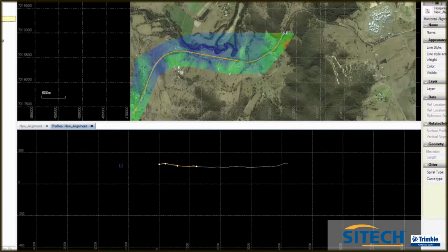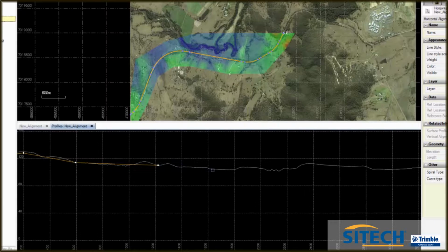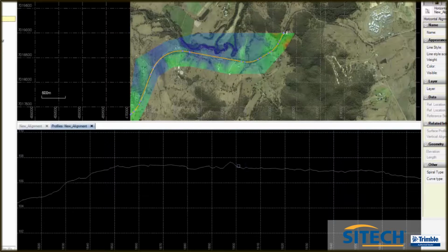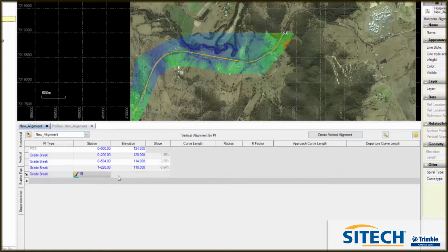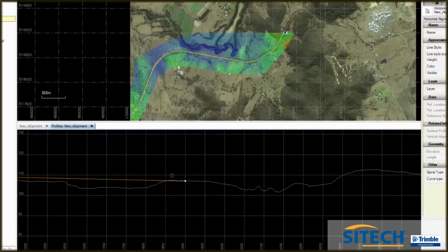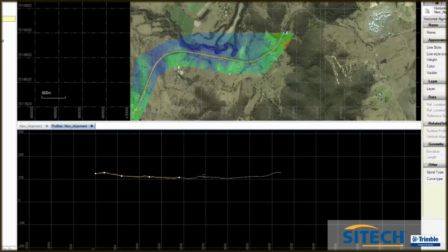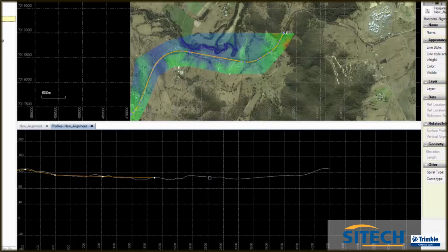Okay, now that's gotten us to there. And the next one needs to come down a little, and it looks like that's the creek area, and that must be the large sweeping curve since that's heading back up onto the end of the ridge. So we'll put the next one around here, so 1900 and 107. Enter those. It's not a big grade break, but you can always edit these as well.